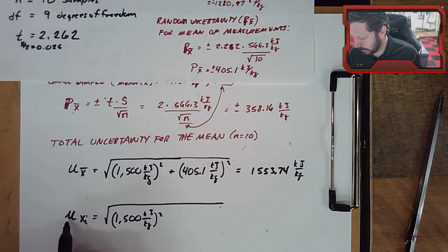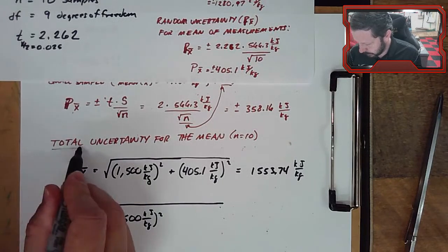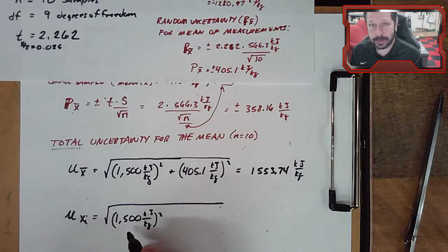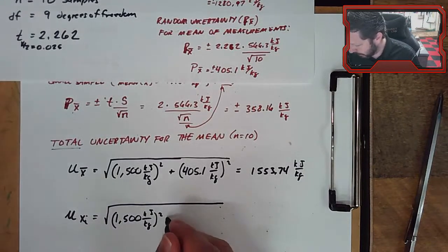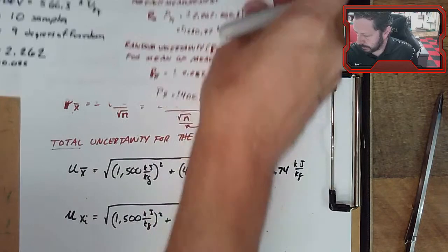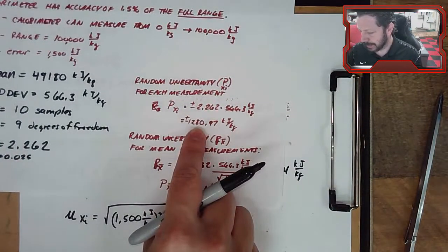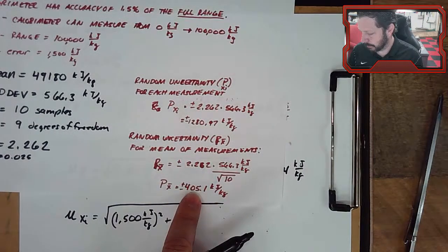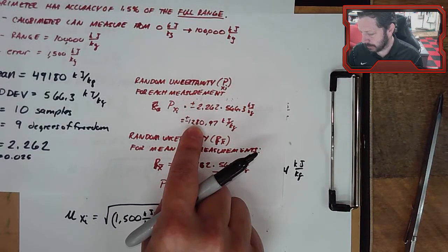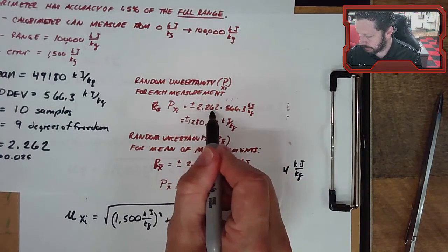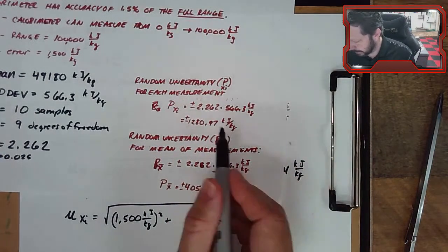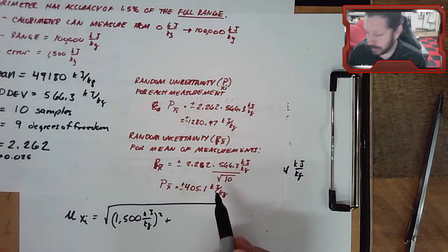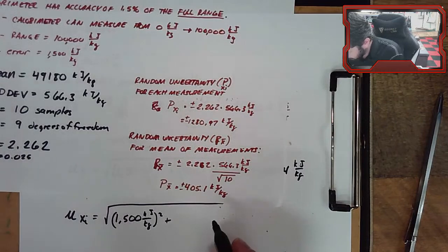All right, so we were doing the total uncertainty for an individual measurement. The tool didn't change, so the bias or the offset error is the same. But when we calculated the uncertainty associated with a single measurement, we did have a different uncertainty. Here was for the group of measurements. Here is for a single measurement. And remember, it's the t value, well, not just the t, it's dividing by the square root of the number of samples.